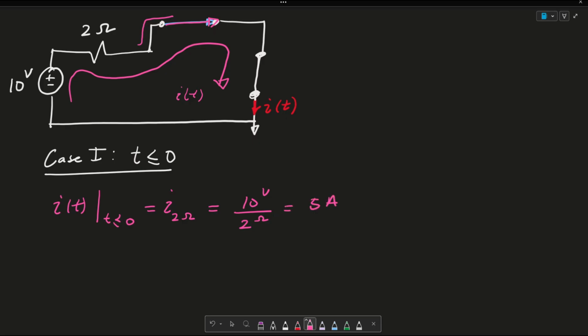And from a past video that I did called What is an Inductor Clearly Explained, again posted in the top right hand corner of this video, we know that current through an inductor cannot change instantaneously. So that means the current I at 0 minus, right before my switch opens, and the current I at 0 plus, right when my switch opens, is equal to the current at 0, which is just 5 amps.